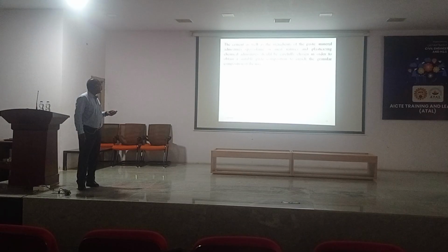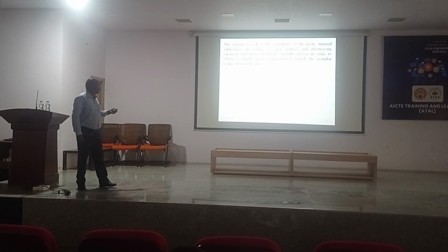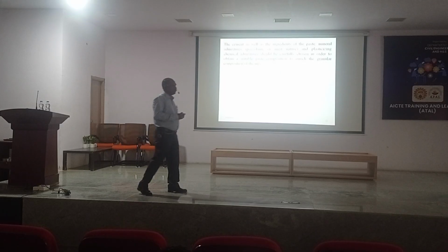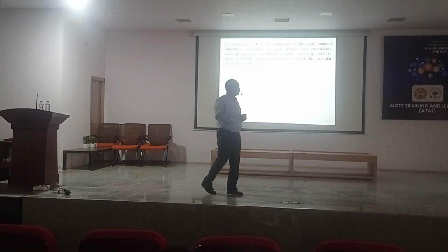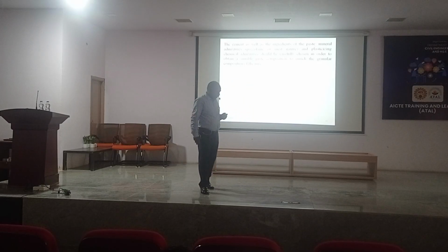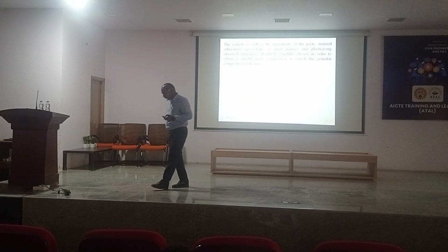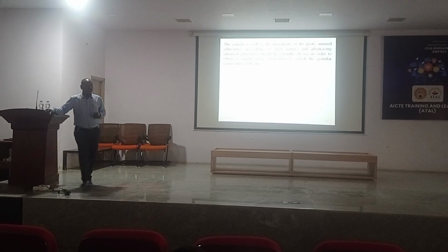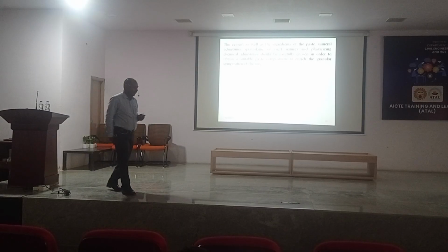Because the cement as well as the ingredients of the paste, mineral mixtures and organic chemical elements should be carefully chosen in order to obtain a suitable paste. Because paste is a very important thing for self-compacting. The rheology of the paste. Rheology means fresh properties. Okay? The basic principle of self-compacting mortar or self-compacting concrete is that the settling velocity of the particle is inversely proportional to the viscosity of the floating medium. Got it? Understand or not?